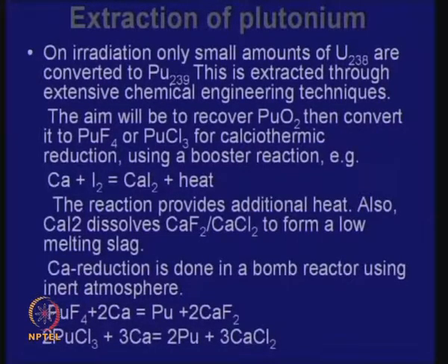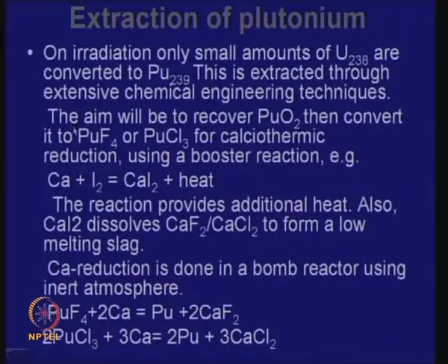In theory, there can be many. We can talk about a metallothermic reduction of the oxide or several metallothermic reactions for the halides, chlorides and fluorides, but calcium seems to be the best bet. Now, here one special technique is used, which is also of general application in many cases. During the reduction of PuF4 or PuCl3, we also use what is known as a booster reaction. Booster reaction boosts the availability of heat, and it does some other things.